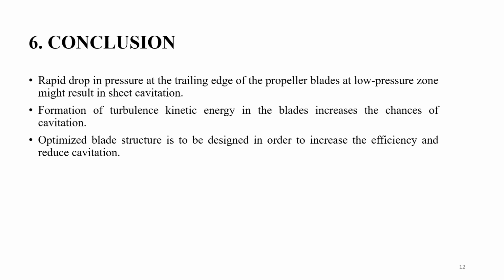Conversely, when the simulation includes a multiphase model accounting for phenomena like cavitation, the propeller's efficiency increases notably to 33.71%. The improvement underscores the influence of accurate representation of fluid behavior on propeller performance, particularly highlighting the impact of cavitation.